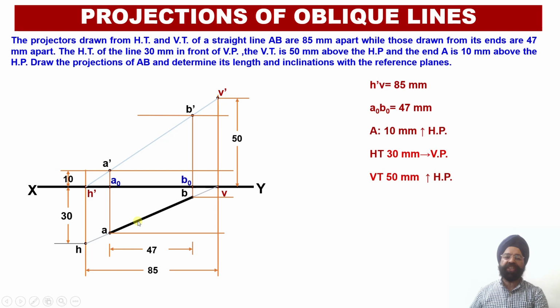This is the plan projection line, and I have been able to obtain the points A and B onto the plan projection line. Now, I can obtain the angle of inclination of this plan projection line with respect to the vertical plane. So this angle happens to be angle beta. Similarly, points A dash and B dash in the front view corresponding to the ends A and B have been located on the vertical plane.